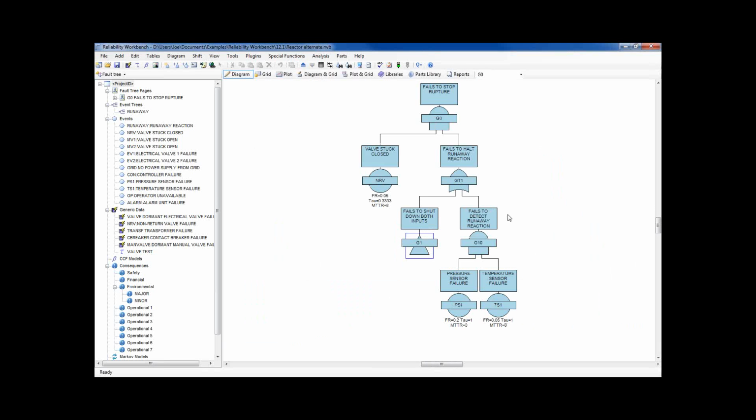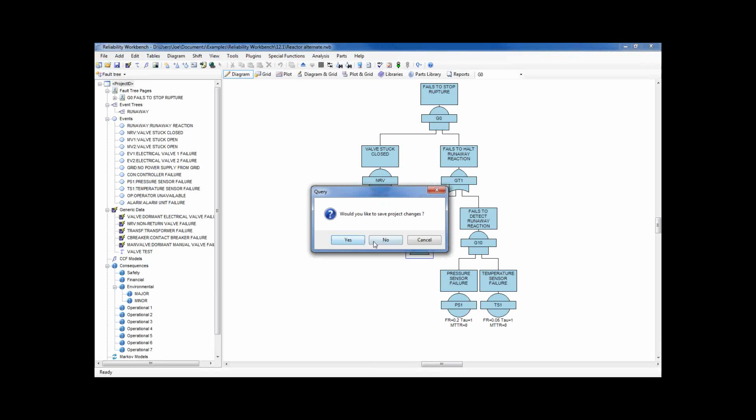And this sometimes makes a little more sense. This is the way safety systems are more commonly constructed. In the fault tree, you have your inputs, in other words, your sensors, and you have your outputs, in other words, the shut-off valves or the actuators or whatever, the pump power removal or something like that. Okay, let me show you an incorrect way of doing it.